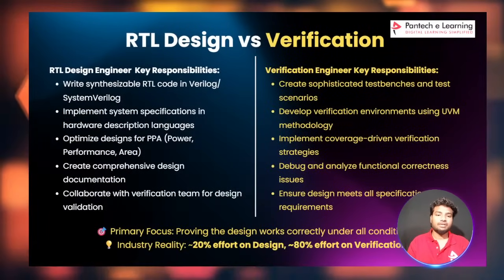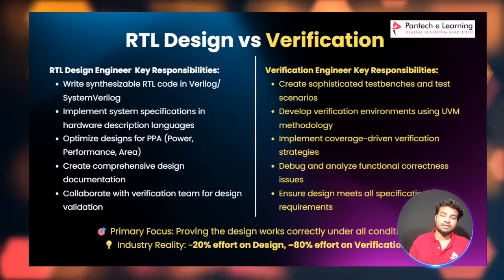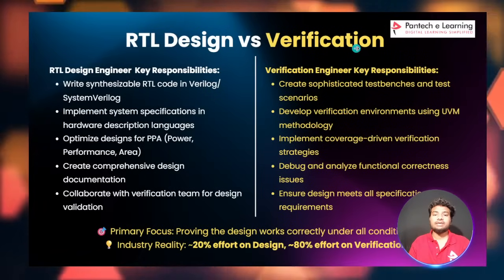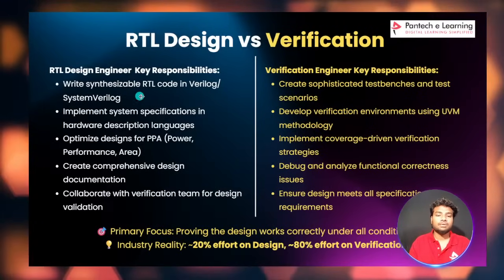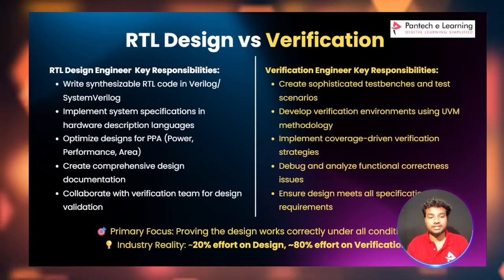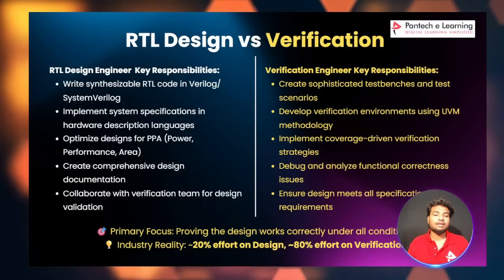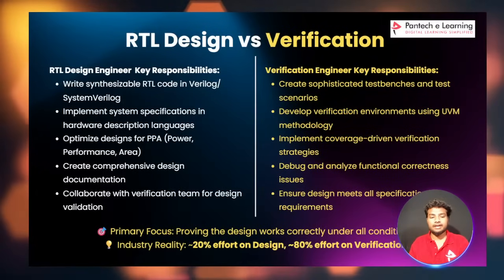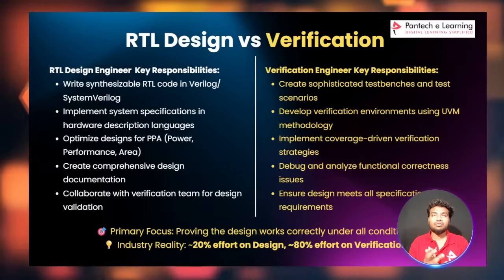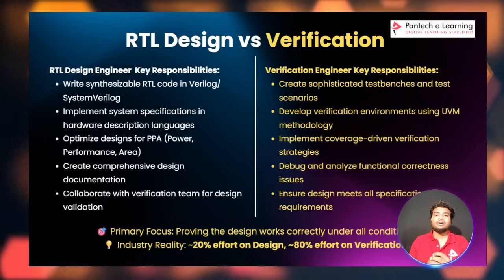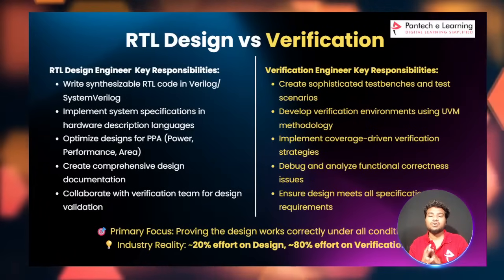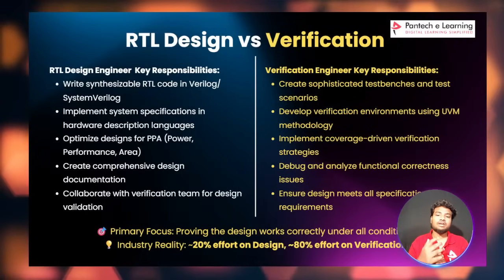And then there is a difference between front end and back end, and RTL and verification. RTL design means writing the design code for the chip. Verification means they will check the design code. Writing synthesizable RTL code in Verilog or SystemVerilog is the responsibility of the design engineer. And then implementing the power performance area, and then comprehensive design documentation, and they have to collaborate with the verification engineer. Why? Because the verification engineer doesn't know all about the design capabilities, design rules and regulations. So for that reason, design engineers have to collaborate with the verification engineer also.